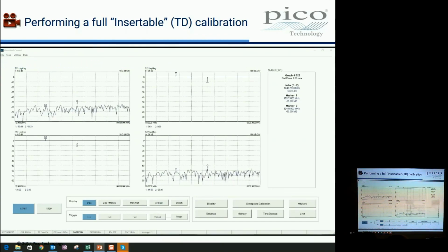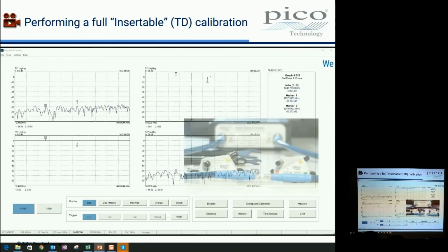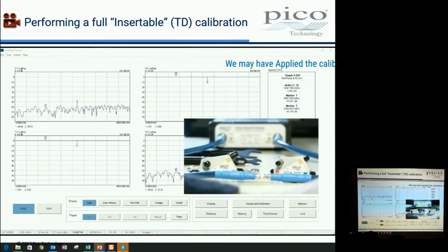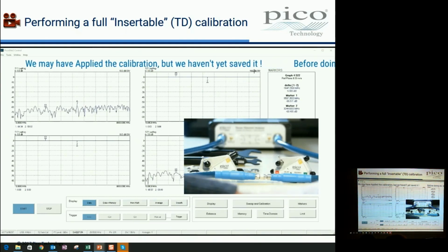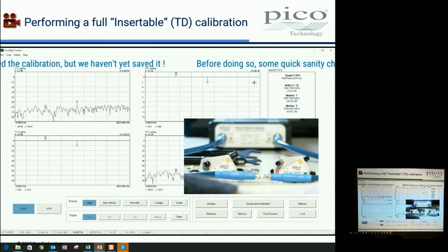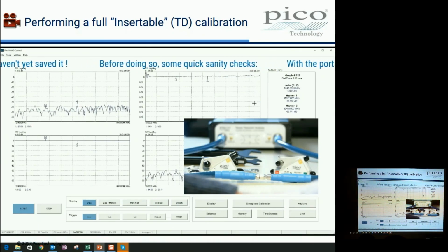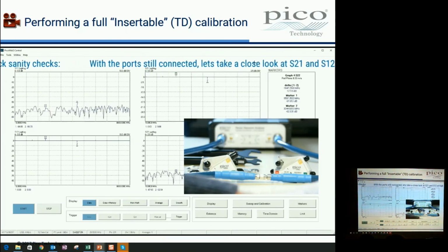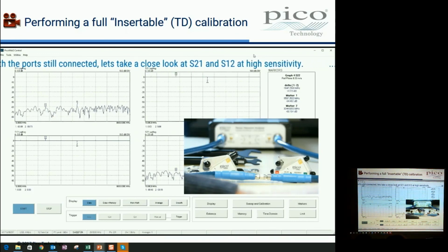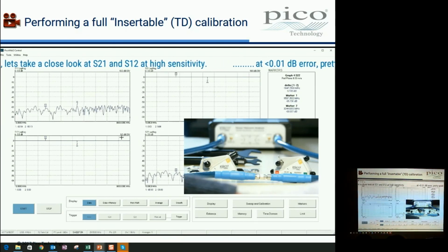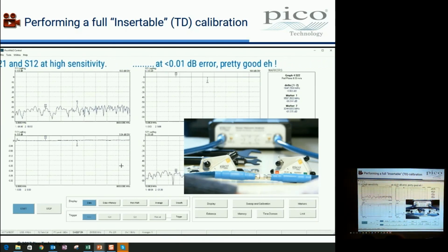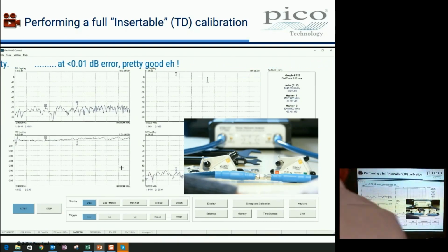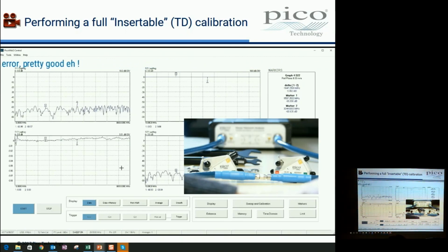This is the sweep and calibration menu. Although it says calibration up there, I've just noticed that. Start frequency, stop frequency, that's for applying the sweep conditions, and we can change those at any time. We can change those having done a calibration, and it will interpolate the data to meet the new sweep conditions if it can. You won't be able to do that if you haven't got the data. If you didn't do enough sweep width and you ask for this down here, you can't do that. But you can change the sweep, and that applies the sweep.